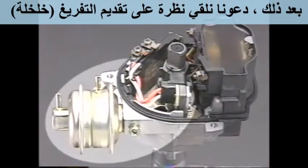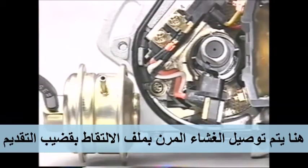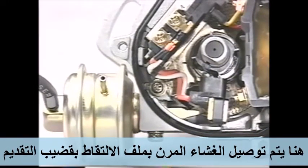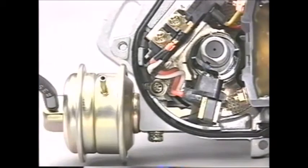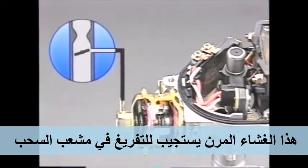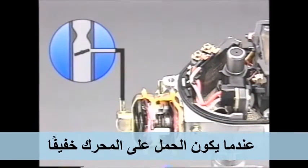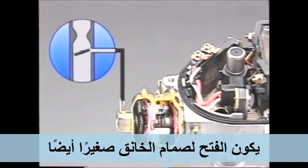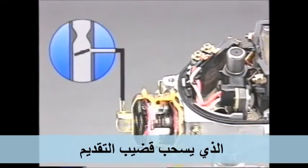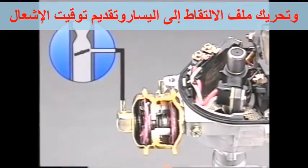Next, let's take a look at a vacuum advancer. Here, a diaphragm is connected to the pickup coil with an advancer rod. This diaphragm responds to the vacuum in the intake manifold. When the load on the engine is light, the throttle valve opening is also small, so a vacuum is generated at the diaphragm, pulling the advancer rod, moving the signal rotor to the left and advancing ignition timing.